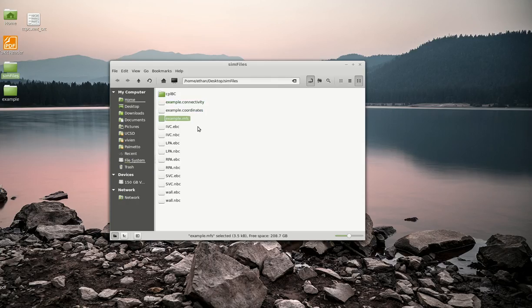We also need this configuration file, the .mfs file. The configuration file will contain information to tell the solver how it's supposed to solve the equations. And then lastly, we need information about the boundary condition. And so we would need two files in this folder. I'll show you how to generate them, but one of them is the initial value file, and the other one is we're going to compile this program.